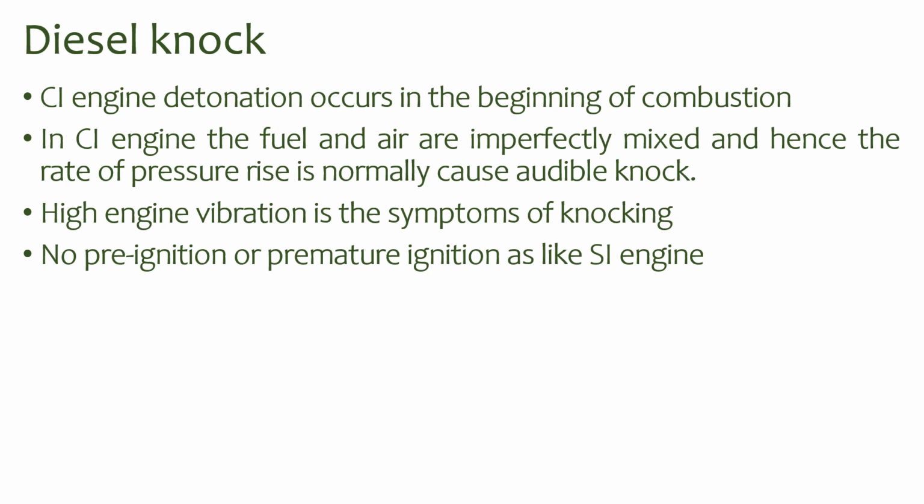Diesel knock. In a CI engine, detonation occurs in the beginning of the combustion process. In a CI engine, the fuel and air are imperfectly mixed, and hence the rate of pressure rise causes an audible knock. High engine vibration is a symptom of knocking. There is no pre-ignition or premature ignition as in an SI engine.